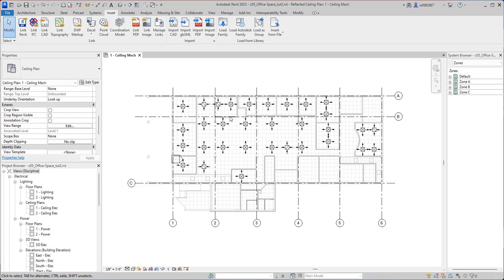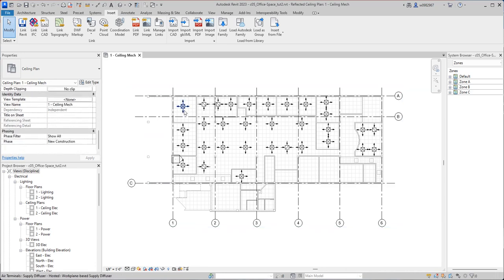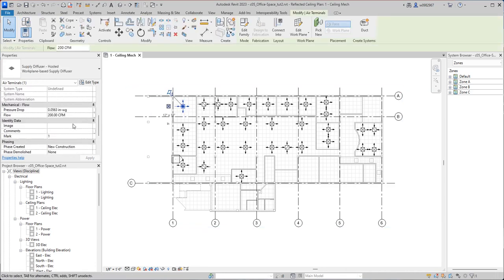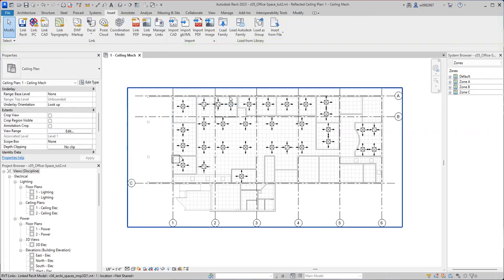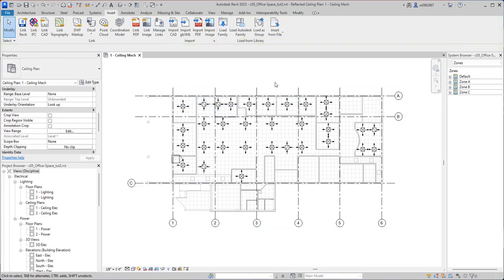the correct airflow. Each one, you can assign an airflow for, and this one the airflow is 200 and this one would be 170. So you can assign different airflows for each terminal, and that is important because airflow means how much air is being moved into and out of the room. So it's very important for a properly designed heating, ventilation, and air conditioning system of your building.